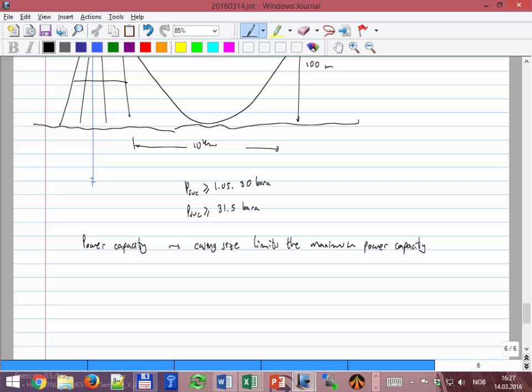And there is also one important factor, that is money. If I want to put a bigger motor, let's say in this field, I'm not sure exactly, it's like 30 wells, I think. If you have to pay that amount of money times 30, then somebody is going to complain. So it also depends on how deep the pockets of the oil company are. And the range of power, they range maybe from 30 horsepower all the way to 1500 horsepower. That's more or less the range, minimum and maximum power.